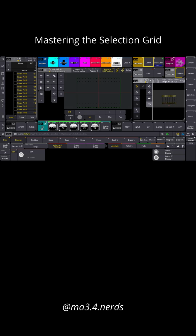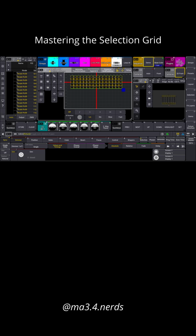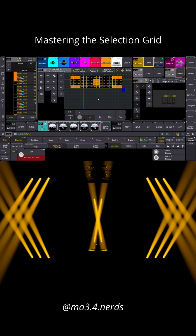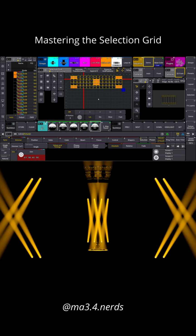So I'll clear out, select fixture 100 again and hit down, and I'll move to my 2D front view, hit the camera to grid again, and then I'll disable preserve grid positions. Disabling this setting simultaneously executes the remove gaps and remove offset function. As you can see, we now have a pixel perfect representation of the stage that I can easily apply any phaser to, while knowing that there will not be any weird gaps in my selection.